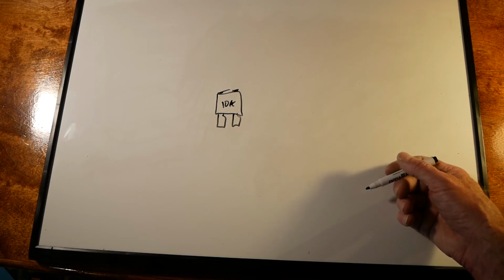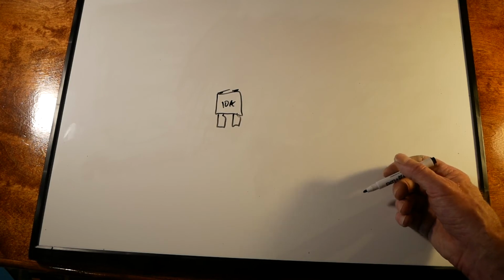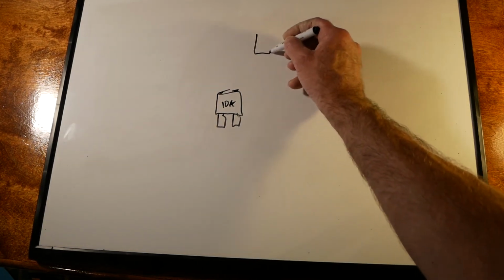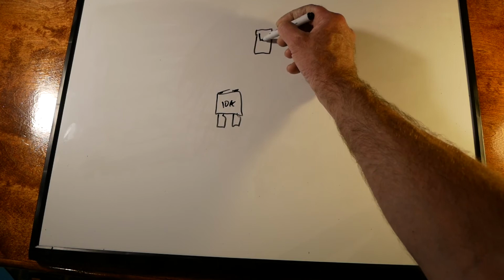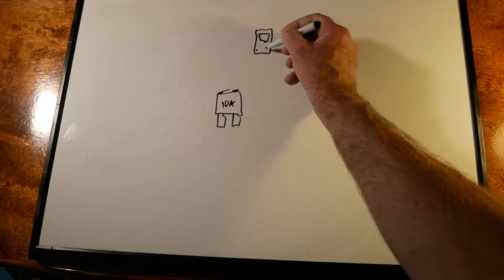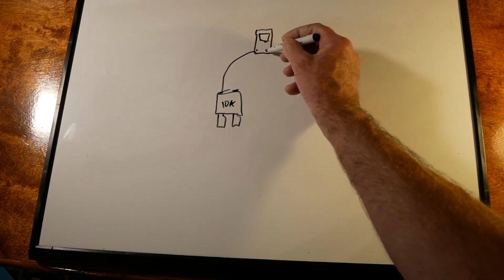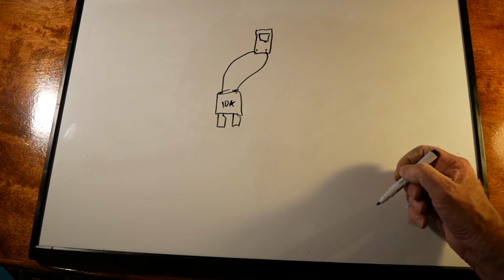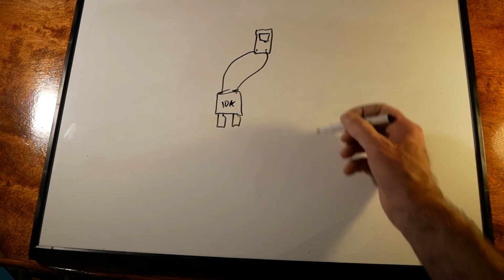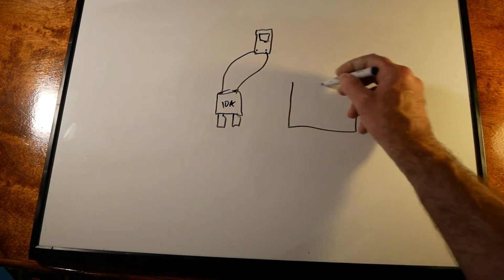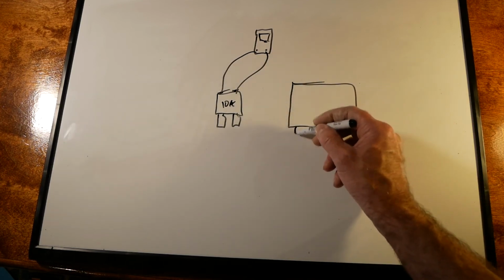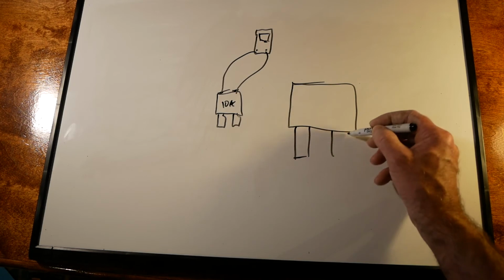So you can't just disconnect modules in a modern car to check parasitic draw. So one thing you can do is just get to the fuse box and you start taking voltage readings across the top of the fuses. All fuses have resistance. So if you look at a typical blade fuse, it looks something like this.